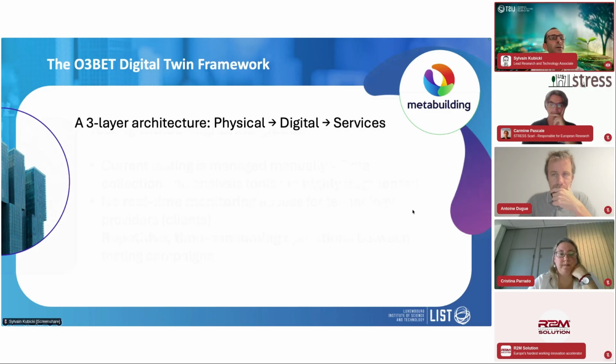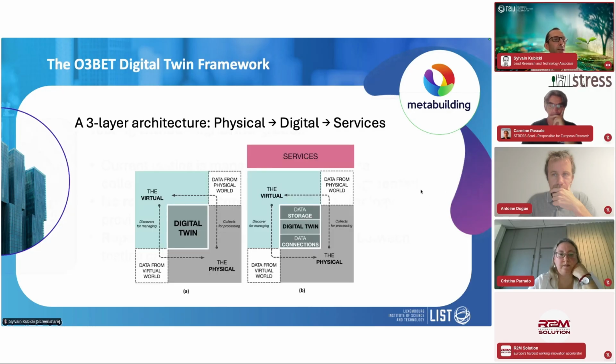At the base, and maybe I can add the image, it's really to leverage on the digital twin paradigm. So at the base, there is the physical part of the twin, or the physical twin, which is the building itself. So you have seen the facade elements that are being under test, the sensing infrastructure itself. And in the middle, the digital twins will develop the virtual models, including BIM model that Christina also showed or mentioned, simulation ontologies that connect those data together. So mirroring the physical assets.